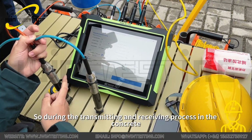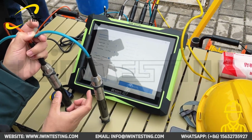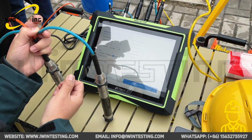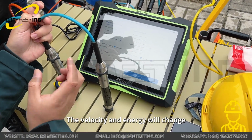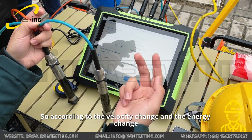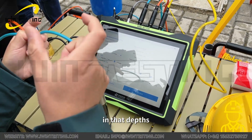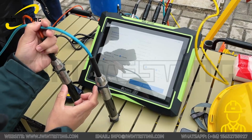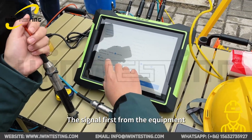So during the transmitting and receiving process in the concrete, if there is any defect, empty space or something else, the velocity and the energy will change, right? According to the velocity change and the energy change, we can know if there's anything abnormal at that depth. What we really want is the thickness of the concrete.